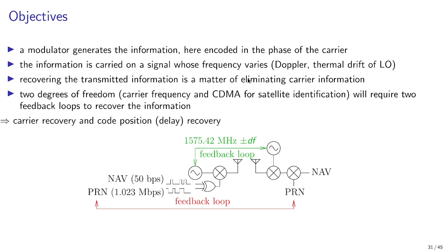However, prior to the Gold code correlation, the signal is below thermal noise and the Costas loop is unable to compensate for the frequency offset. So we now have a chicken and egg issue because we need to compensate for the frequency offset to accumulate energy of the pseudo-random sequence, but the pseudo-random sequence energy can only accumulate if the offset is compensated for.